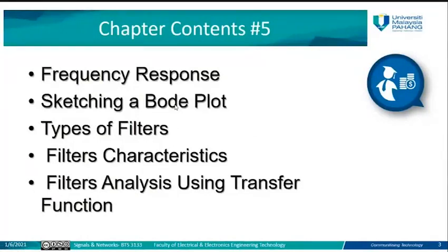We start with the frequency response and its definition, and how we can find the frequency response for a specific system. Then we are going to learn how we can draw or sketch the Bode plot from the given transfer function.